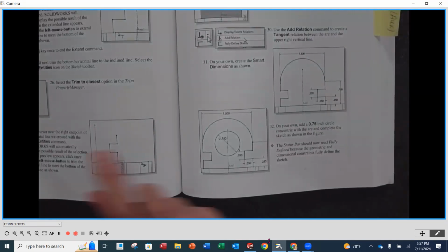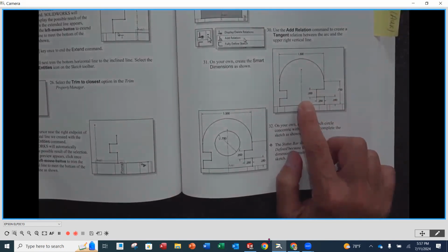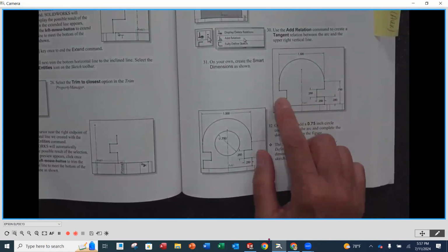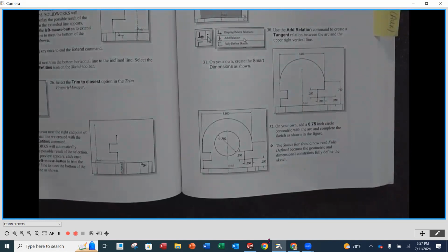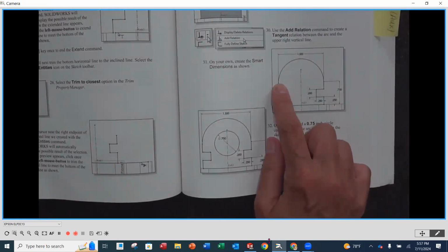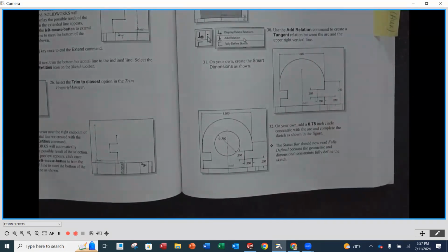I'm going to put an axis in here, a center axis. Then we're going to use that dynamic mirror function to sketch the profile up to underneath where this arc is going to start. So we're not going to do the arc. We're just going to go from here out and up, and then stop there. Then it's going to mirror on the other side at the very same time.